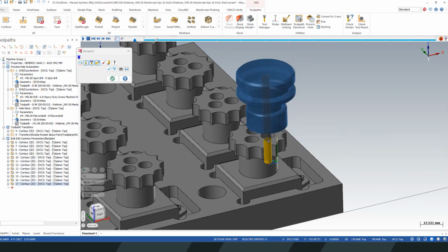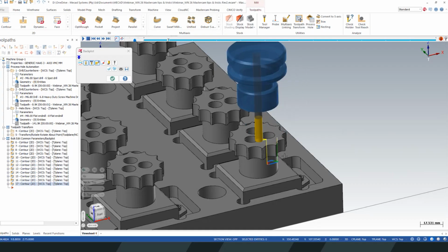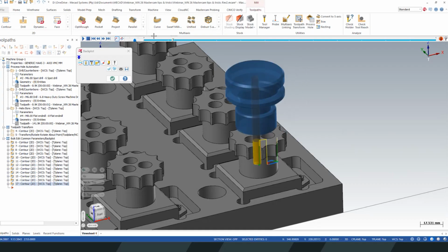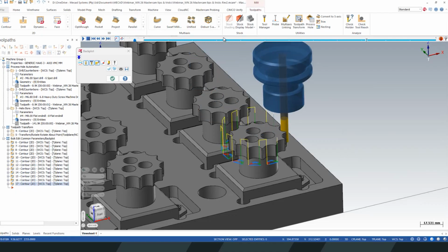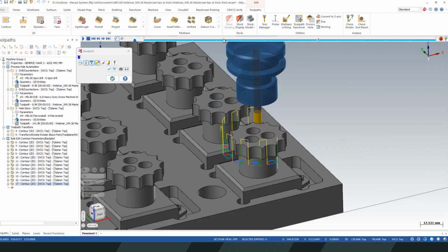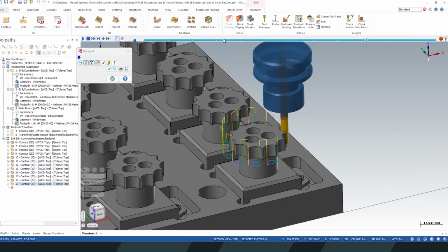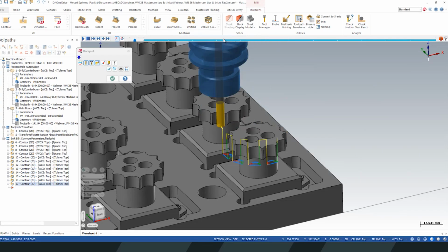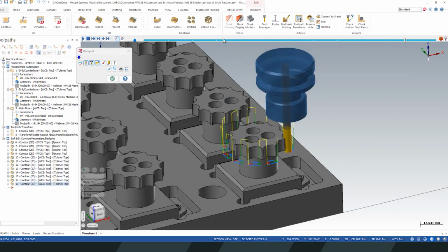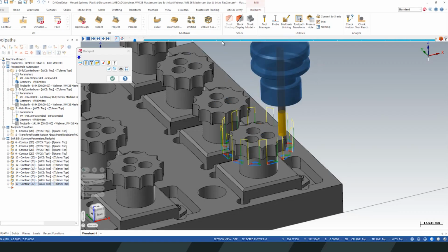Now another interesting feature, which is probably the most useful, is if you take your mouse and hover over this blue bar, that is where your timeline is, and you scroll up and down, you can scroll back and forth on a toolpath. So if you still want to control the toolpath, but you don't want to click S and B, you can just go up here and scroll back and forth to be able to see your toolpath. This is especially handy if you have a big toolpath.